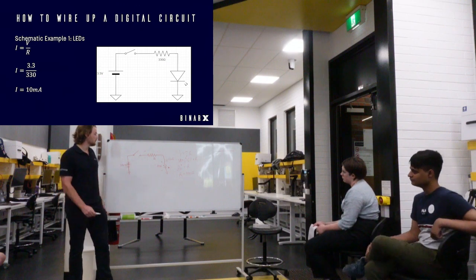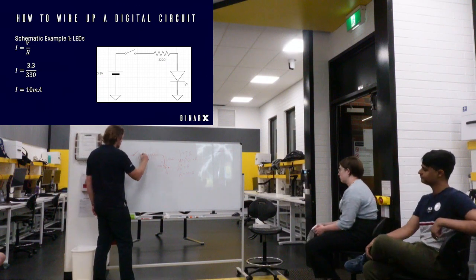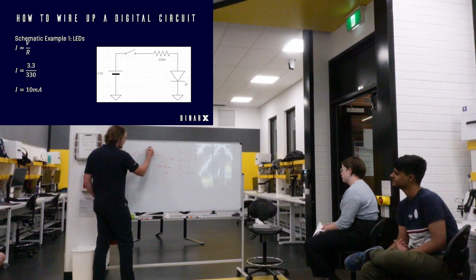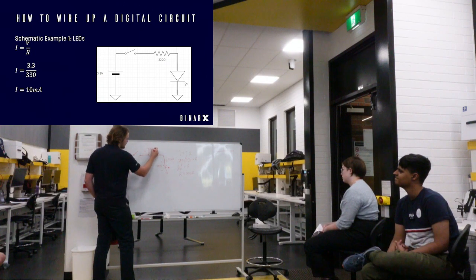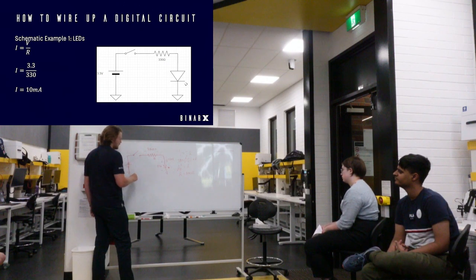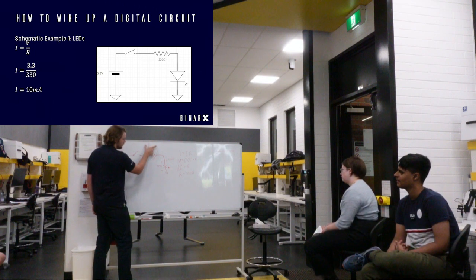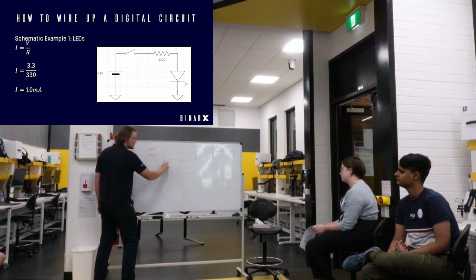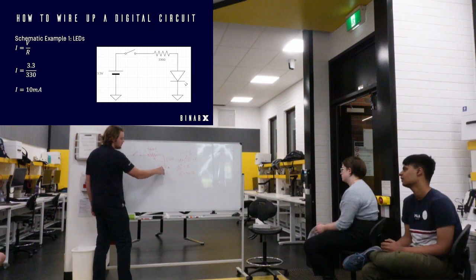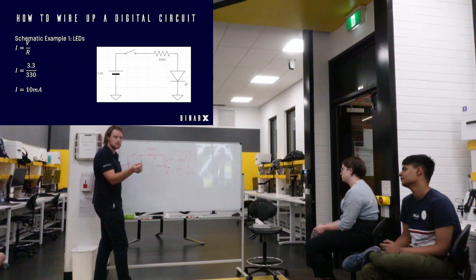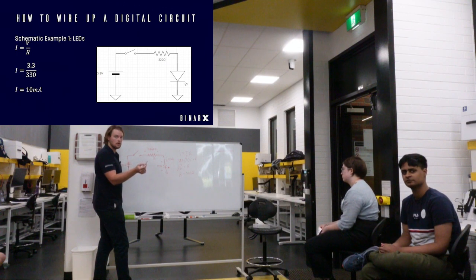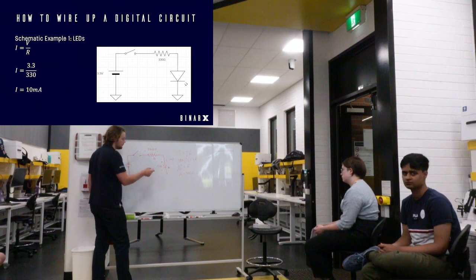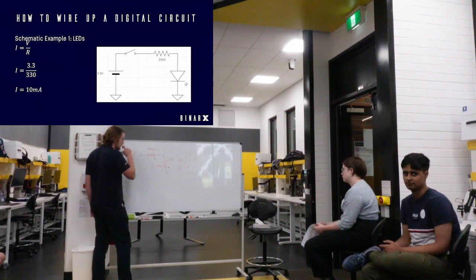Okay, so technically the voltage across this resistor is going to be 3.3 minus 0.7, because in series, remember we're talking about resistors, the voltage will drop across one resistor and then the other resistor proportionally. But with diodes, we know it's a fixed 0.7. Can I assume 0.7 is fine? They've got a few diodes, different colours, they have different forward voltages. But in this case, you could just use 0.7 and they'll know to adjust it for their forward voltage drop.